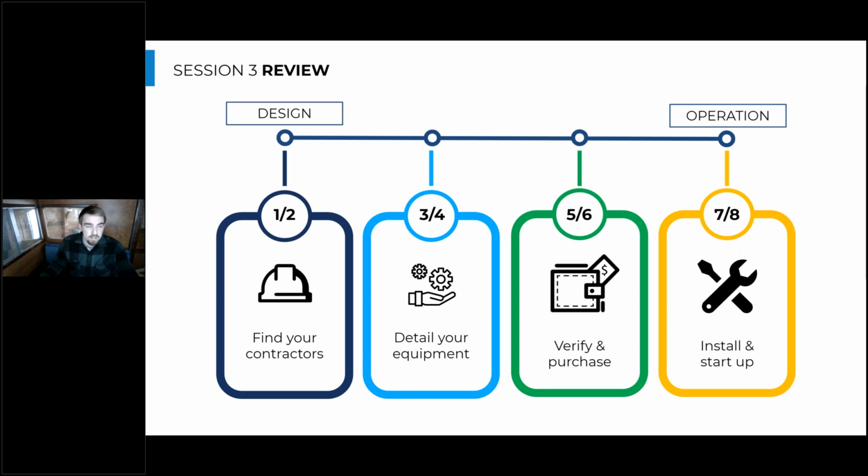We also talked about the detailing of the equipment and working with the manufacturer and the designer to figure out how you need to accommodate your equipment to make sure that it fits the designer's intent. There are little tweaks and details that you need to think about when it comes to how you're pairing your storage and your other components with the heat pump water heater, as well as any additional options you might need to make that water heater function in the context of the designer's sequence.